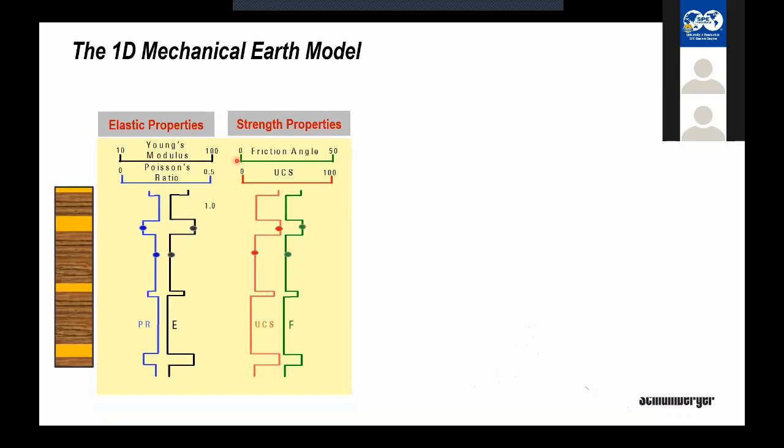It's clear, right? Okay, cool. So Poisson's ratio is also called the fattability parameter. It tells you how much lateral strain there is, how much your rock is going to spread out when you apply a certain stress. Shales in general will have relatively higher Poisson's ratio.